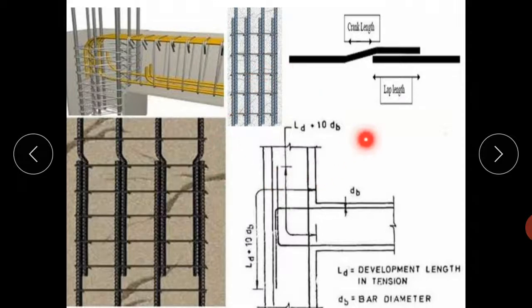When we consider a beam column joint, a certain amount of extra length is required to be embedded, that is known as development length. It is required to establish bond between steel and concrete. It also transfers the load from beam to column. It prevents the bar from pulling out under tension.